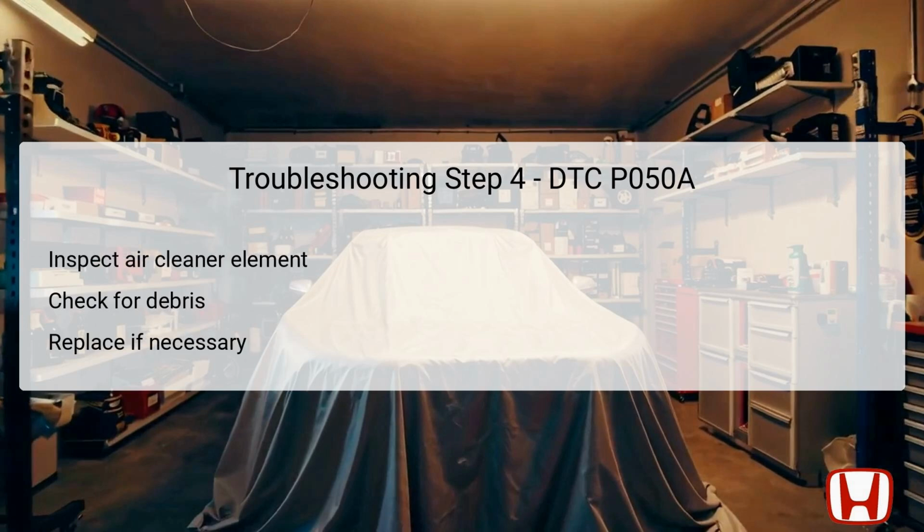In this step, focus on inspecting the air cleaner element for dirt or debris that could inhibit airflow. A dirty air cleaner element can prevent adequate amounts of clean air from reaching the engine, negatively impacting performance. The element must be checked thoroughly for any obstructions. If it is found to be dirty, replacement is necessary.